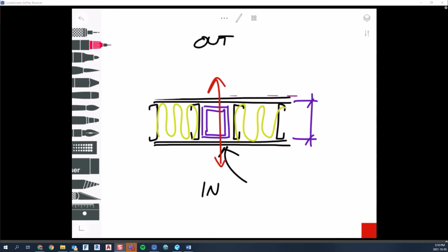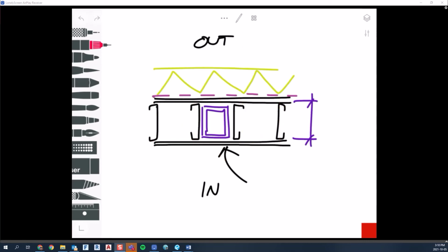And you're also going to have heat loss at every single steel stud going through your wall. Because everything's steel, it's got a high conductance, so there's a lot of heat loss. So it's almost pointless to be doing that. It's really terrible. So outside insulation is the best approach, and that's generally what we're seeing around town right now.